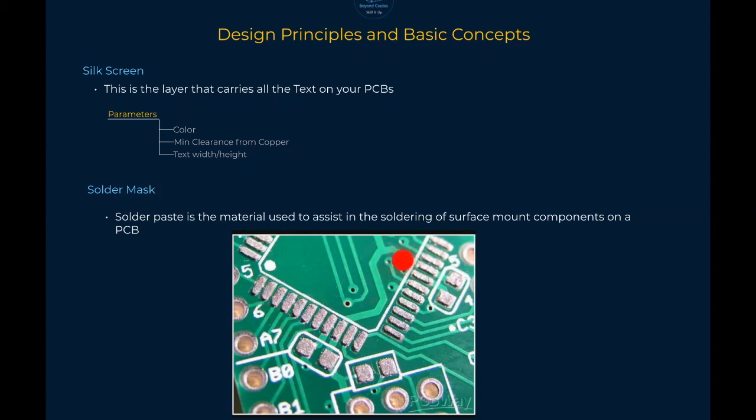Once they place the components here and apply heat, the solder paste is going to melt, forming together and binding the pads so nicely. That's why when companies make your PCBs, it's nicely done, because they put it in the oven so that the solder paste will melt nicely and form a very good joint with your pads.